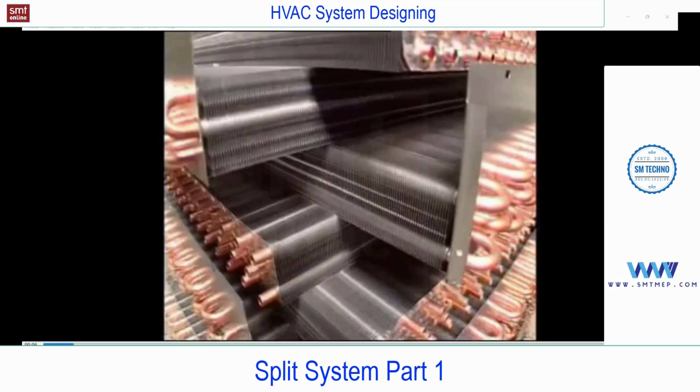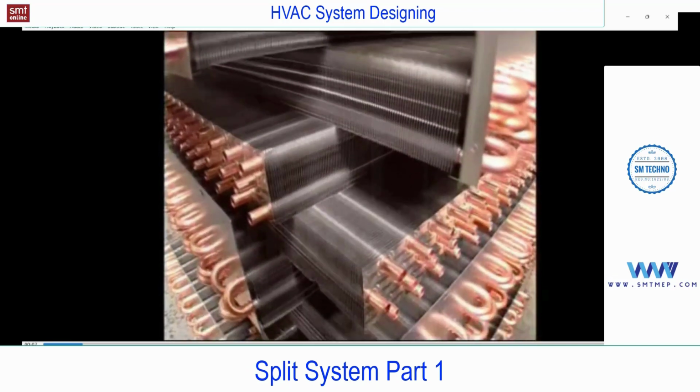So if the outdoor unit is placed in humid areas and it is aluminum, the life is going to be less. So in that case even the fins are made of copper or with an additional coating. That depends on the model. But from an interview point of view, the default configuration is copper tube with aluminum fins, for condenser as well as evaporator.